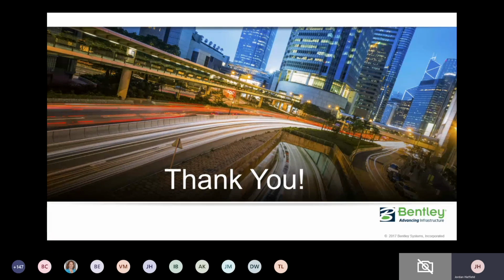The corridor is in a cut section. Will it clip the reality mesh? So you would not be clipping. It would just be like an active terrain. So it would not be anything that you'd be clipping. That would still be your existing surface, and then you would have your proposed surface that would cut through, and then your back slope would tie back into that reality mesh.